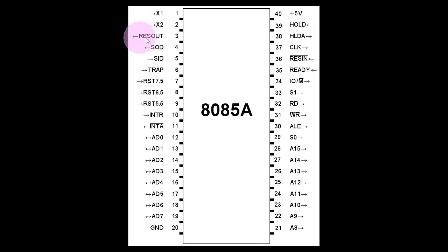And the second usage of this is, with this microprocessor being reset, if there is a reset button available in the external device, that reset output will also reset it. So this is about starting and stopping your microprocessor. Once power supply has been given and clock is being applied, if you want to reset or restart your microprocessor, the reset in pin is there. The reset out pin will perform the function of resetting every other device connected to this microprocessor if it needs a reset, or the devices will know that the microprocessor has been reset. So whatever their internal mechanism is, they will again give their task to this microprocessor for doing, right?